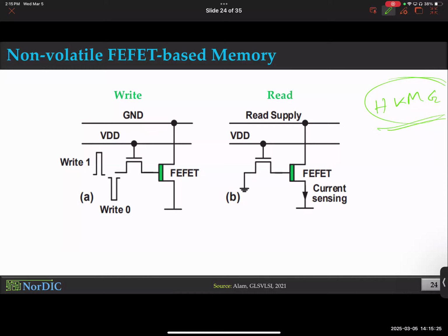If somebody asks, hey, what type of transistor technologies are we using? We are all using HKMG. For the last 10, 15 years, we have been using HKMG. What does it stand for? Can anybody tell me? High K, what does MG stand for? Metal gate, remember? So we used to use a polysilicon gate at some point, then we switched over to metal gate.